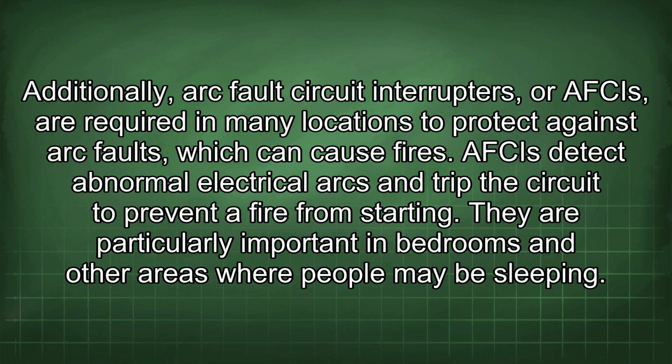Additionally, arc fault circuit interrupters, or AFCIs, are required in many locations to protect against arc faults, which can cause fires. AFCIs detect abnormal electrical arcs and trip the circuit to prevent a fire from starting. They are particularly important in bedrooms and other areas where people may be sleeping.